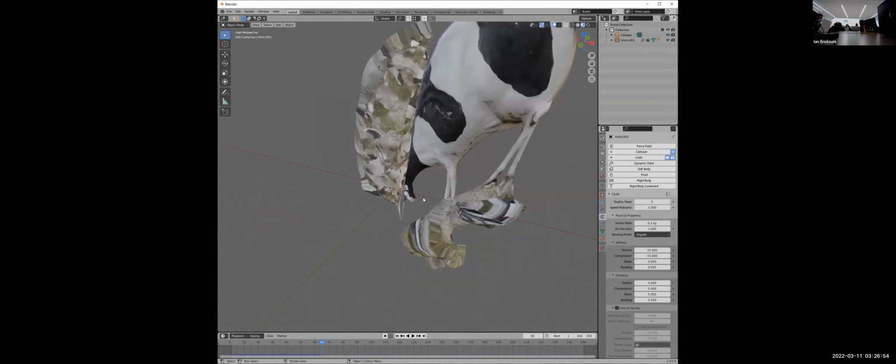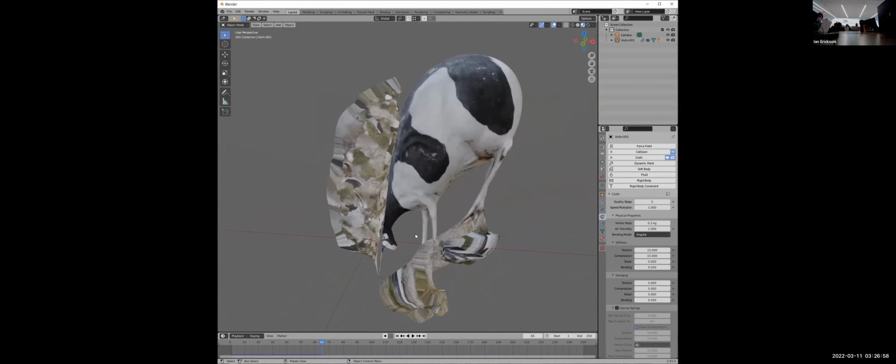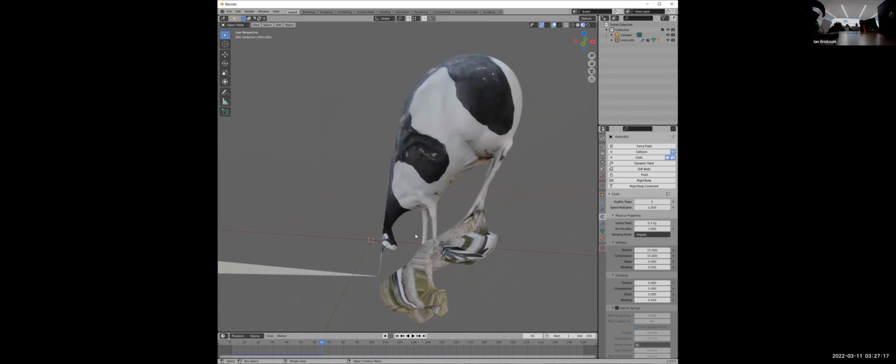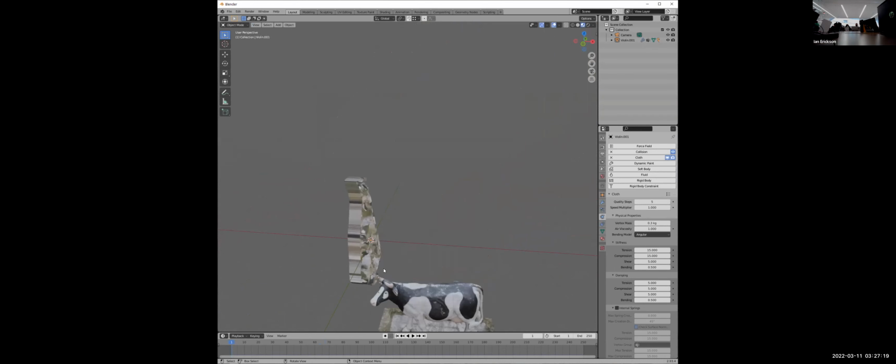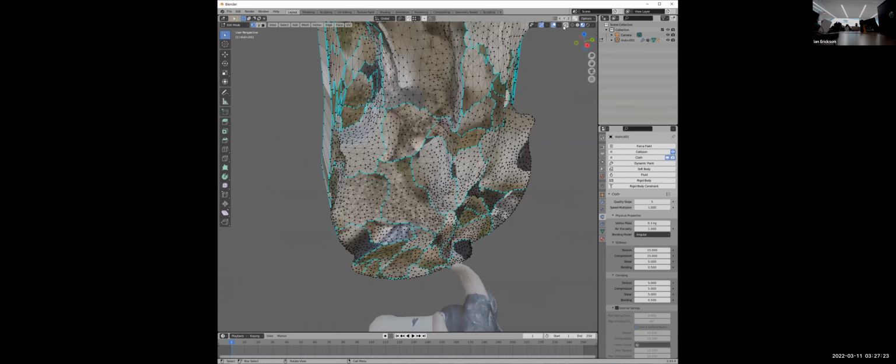Do we have any questions about this right now? I have a question about selection. When selecting vertices, if you select on one side of the cow, it seems like it highlights what you can see. And then if you try to go to the other side, it isn't selected. Is there a way to select all? Yeah, you change your viewport to the wireframe looking one. Okay. And then you can see everything at once. And then when you drag click it, it'll get everything. Awesome. Okay. Exactly. Good.